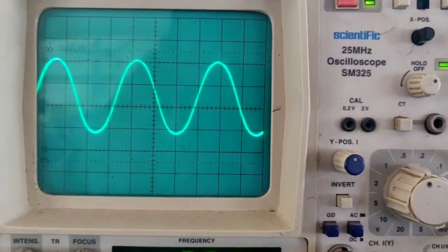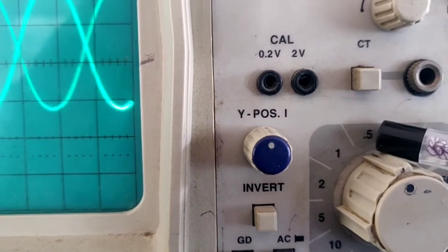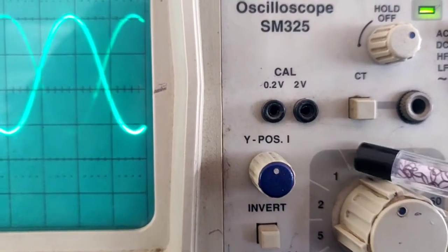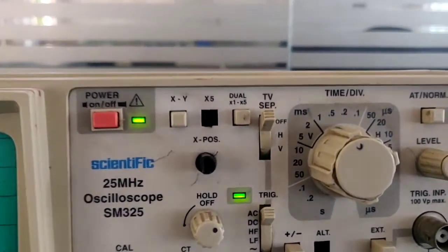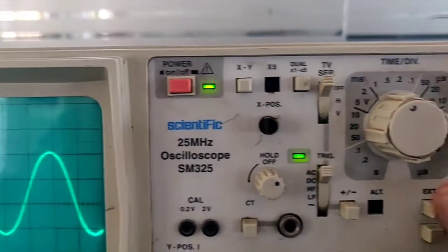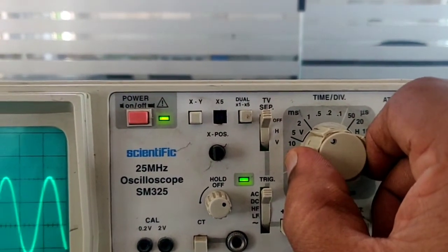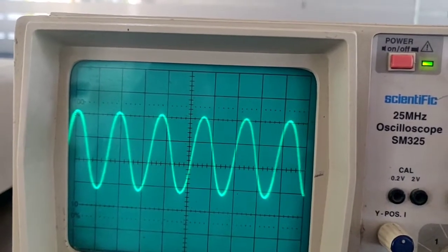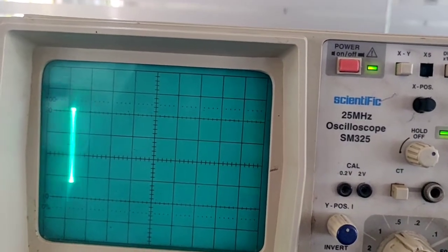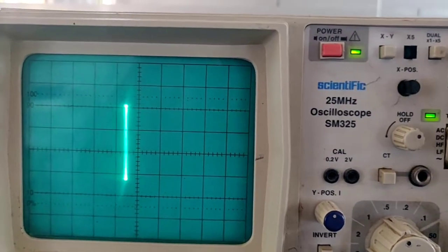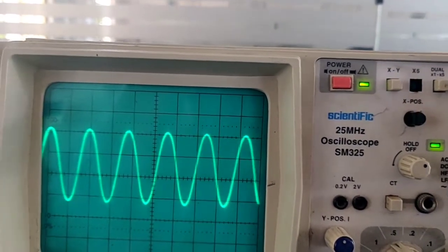Okay, for the time being I am going to select this. So what is the scale here? You can see that, 0.5 volts. I have selected the 0.5 volt scale, and let us go for the time base control here. See that time base control, I am going to adjust this. Which time base scale do you have to select? Assume that this is an unknown value for you. If you select the least value, something like this, see the waveform, you can't read the frequency. So keep on changing this, and finally at one stage this is okay.